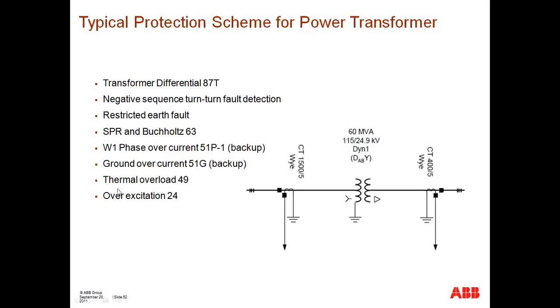What this will do is monitor your volt-hertz relationship so that we're taking into account the amount of excitation current that flows into the transformer, and we can make, again, slow tripping decisions in regards to that to avoid further damage to the transformer. So this is a pretty standard package that's deployed along with transformers.